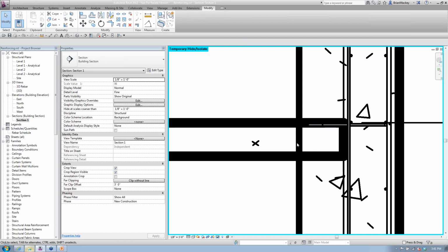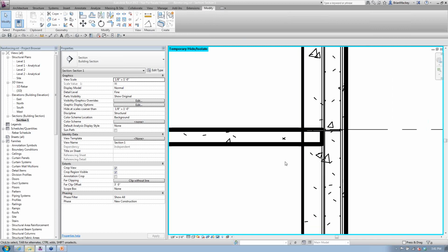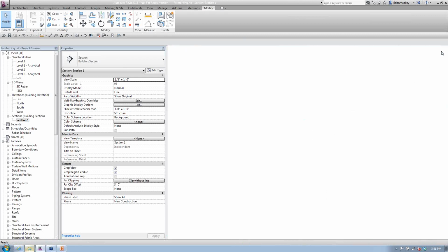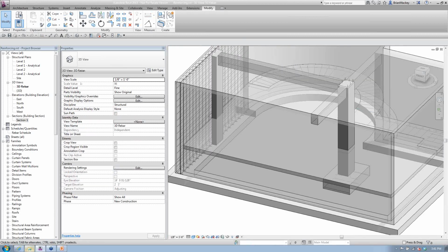So it's going to depend on how you want that to look. Do I want it to cut through, not cut through? Is it going to matter when I go through and do that? That's also a way to avoid having that happen in the structural column schedule, the graphical column schedule. If you don't want that to be displayed, you can choose to unjoin that, and then your graphical column schedule will look a little bit better too. So I just wanted to point that out, because in my opinion that can definitely be an issue when you start dealing with floors going to slabs.